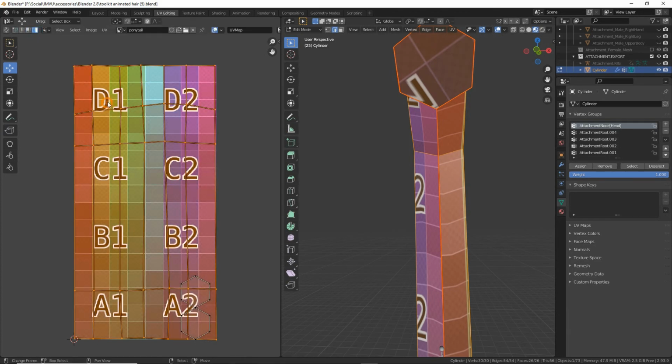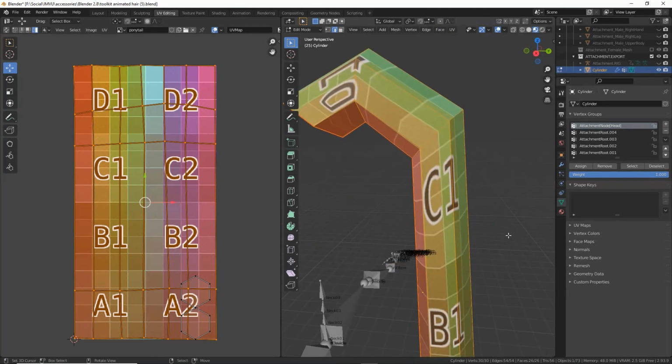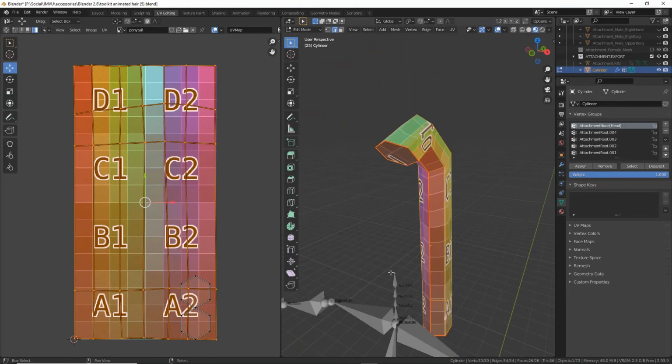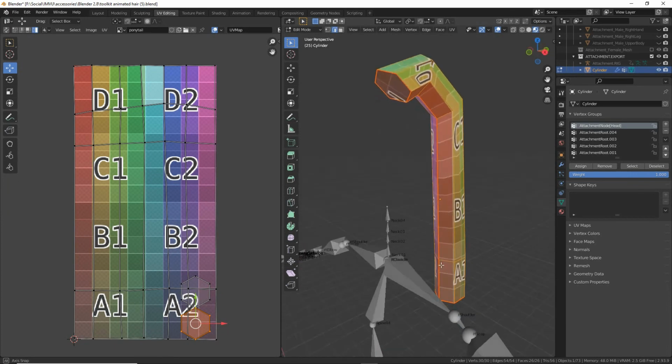So let's just switch to island. So that's the UV mapped to the bounds roughly. Obviously spend a bit more time doing that, but that's the bounds of the image mapped one-to-one to our mesh. We don't have to worry about these two because, as we said before, they are not used. So we can either map them and just push them into a corner, it doesn't matter where they are, or we can delete them.